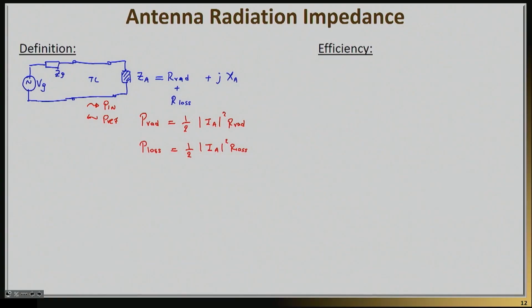So it's actually this first equation that you will see here that basically forms the definition of the radiation resistance. In other words, the radiation resistance is essentially a fictitious resistance that would have consumed the same amount of power that the antenna is radiating. So the radiation resistance has units that are, of course, ohms. And most people, when they talk about the radiation resistance, calculate it exactly by this equation that you will see here. Similarly, the effective losses of the antenna that are related to the efficiency we were discussing in a previous lecture are essentially given by this equation here.